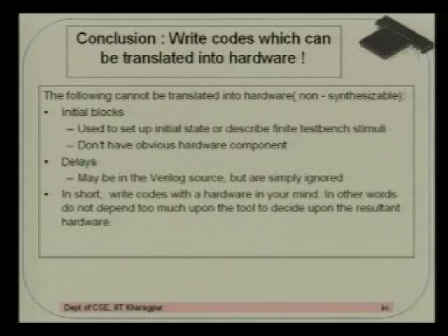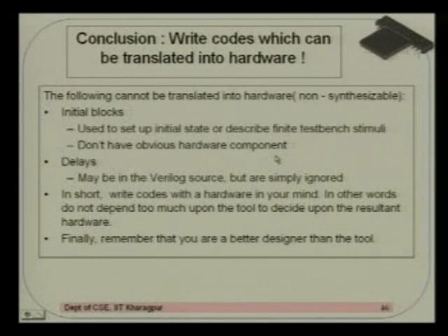First you should think of the hardware, that 0th step is very important. You should think of a good hardware, and then only write Verilog code or anything, and go into the design flow. In other words, do not depend too much upon the tool to decide the resultant hardware. And finally, remember that you are a better designer than the tool. The tool is used to assist you, do not blindly rely on it. It's not a magic potion where I define what I want and it will give me a design. No, I am the designer.